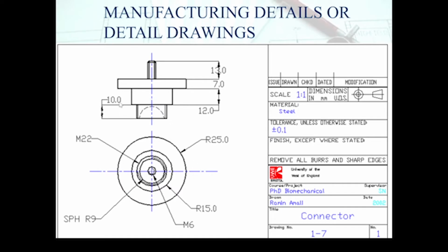If you were to draw projectors, it would all end up with the same drawing. So that circle right there is R25, meaning radius 25, and if I were to draw some thin lines here, that projects back into this slice, which is 7mm thick.